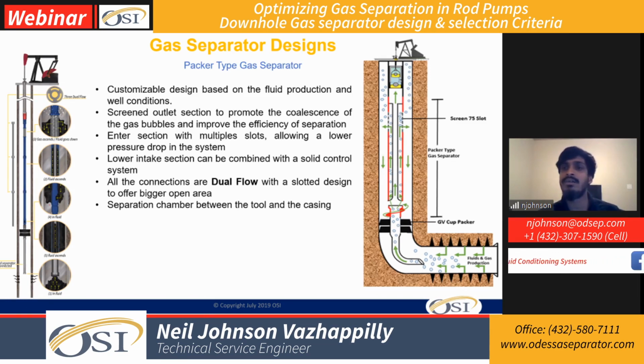Dual flow is something that Carlos mentioned previously, but the dual flow actually has 2 functions. The number 1 function is when the fluid is going through the gas separator, these 3 ribs that you all see on the dual flow help in the baffling of gas. That is one of the design principles used for the majority of the gas separators, as Carlos mentioned before. So having these dual flow connections helps in breaking out the solution gas that is in the fluid, right? So that is one function.